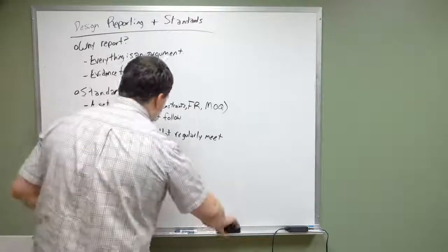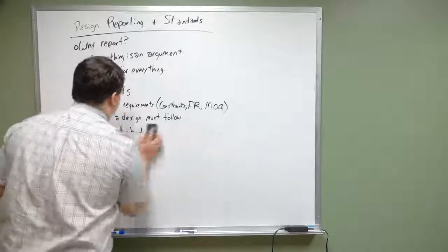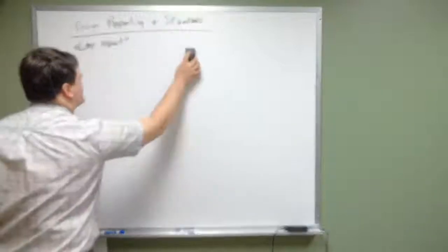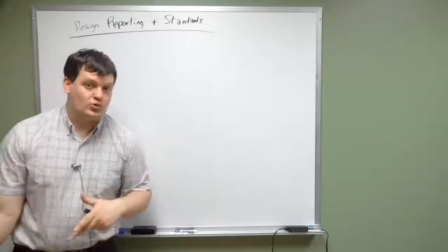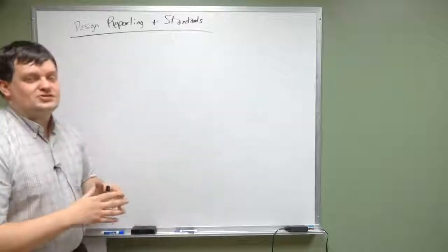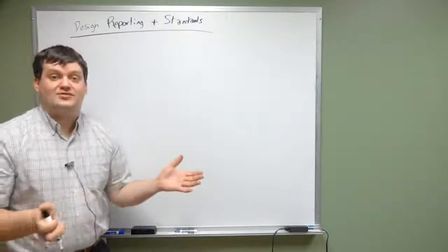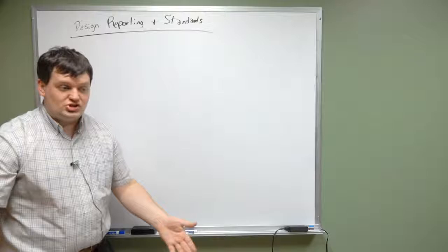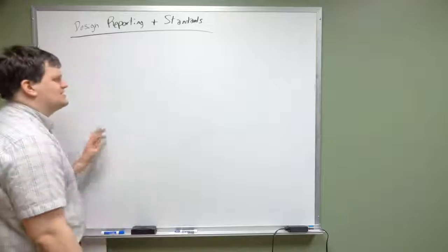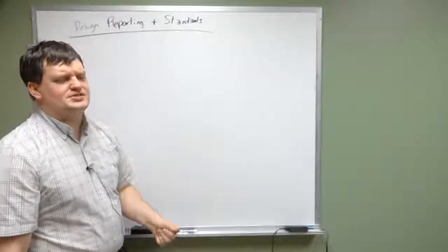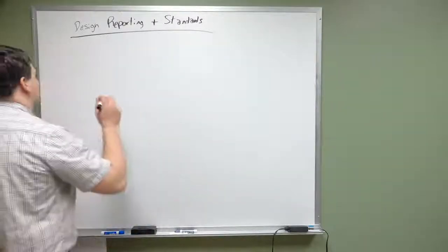Okay, so how do you report? What does reporting really look like? If you're using standardized hardware, you should be able to access a standardized report. That is one of the nice things about that. Standardized reports give minimum stress strain requirements, and if you buy a bolt that doesn't have the minimum stress strain requirements from a company, you can actually sue that company for producing errant hardware. That's one of the nice things about standards, is it removes the liability from you, the designer, and puts it on the manufacturer. So it's kind of a double-edged sword there for them, but it's whatever.